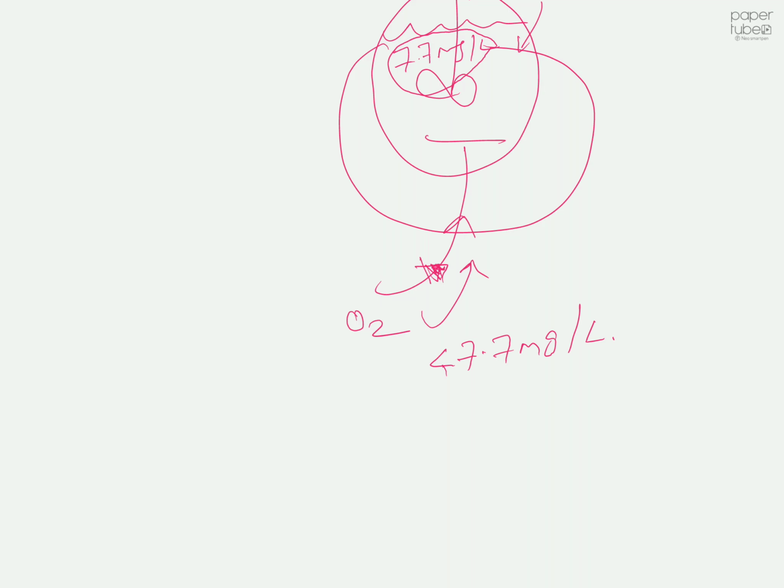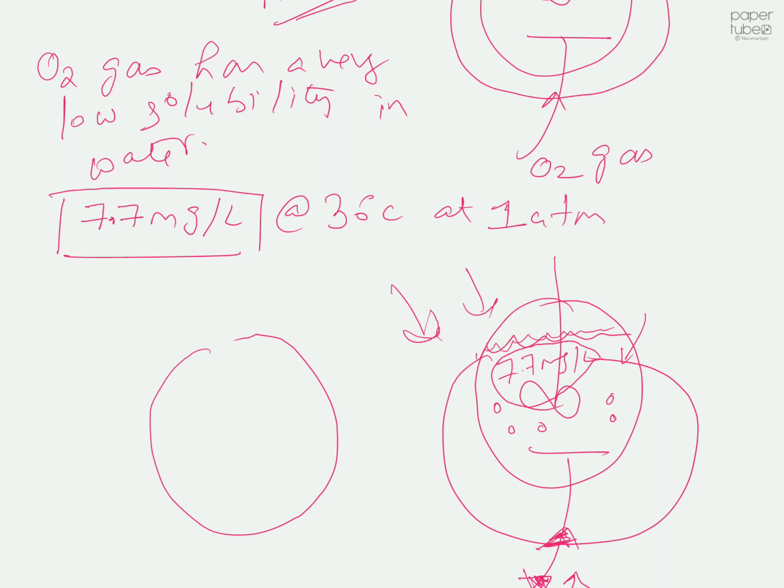So the real issue here is not this. One issue is the very low solubility of oxygen in water, and another issue is, imagine you start an experiment. Let's use the same reactor which I drew here, and you have a very low cell concentration inside, and you supply a lot of oxygen. So the oxygen concentration should be more than enough for the cells to breathe, to respire, and then they can multiply, so that they can convert your reactants into products.